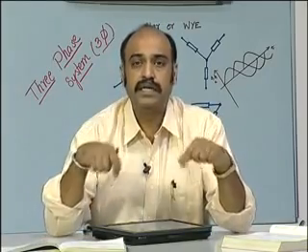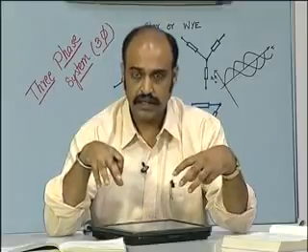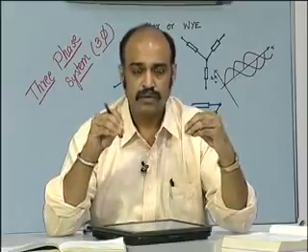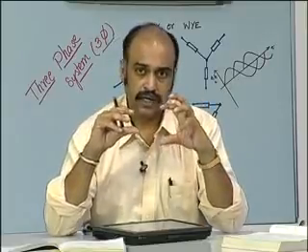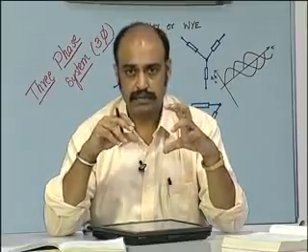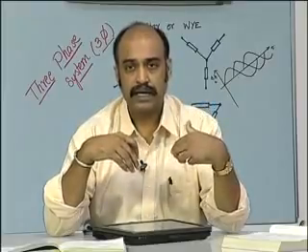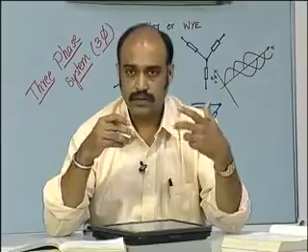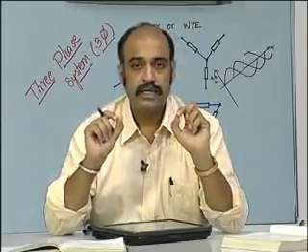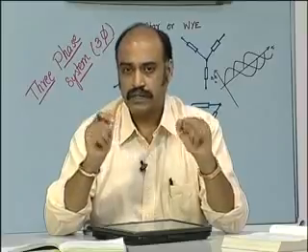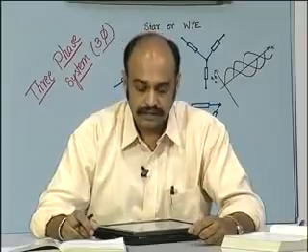Internally inside the machine, inside the armature, the currents that are flowing in the coil are always AC, but only by means of the device called the commutator, which we have discussed, and the brush combination, external to the motor in the electrical circuit or external to the generator in the electrical circuit, the signals are DC. Otherwise, within the motor, it is always an AC signal.